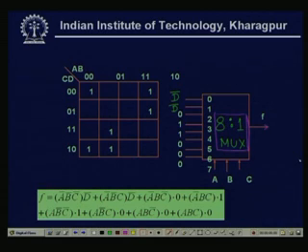We have taken among the 4 variables, 3 as the select inputs, and the inputs are treated as the 0, 1 combinations of 0, 1 and D and D bar. For this particular example, there is no D, only D bars are there. So, in this way we can design any n variable combination circuits using multiplexers.